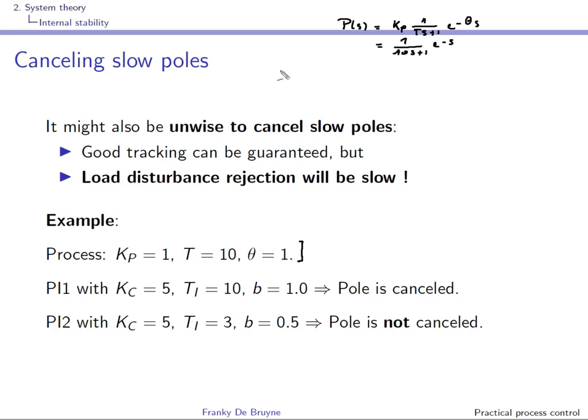And we'll use a PI controller. We haven't reviewed the PI controller, but the PI algorithm that we'll use and that will be introduced later is this one. It's Kc, the gain of the controller, times E of P. This will be the proportional term. I'll come back to E of P later, and then plus 1 over Ti integral of the error.